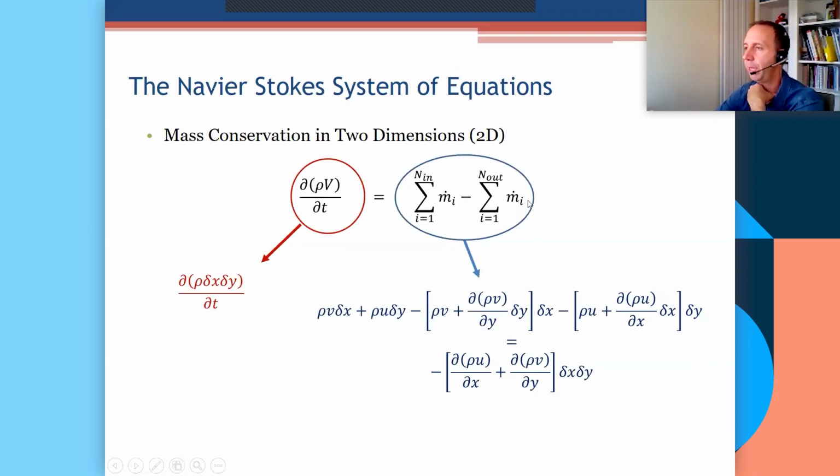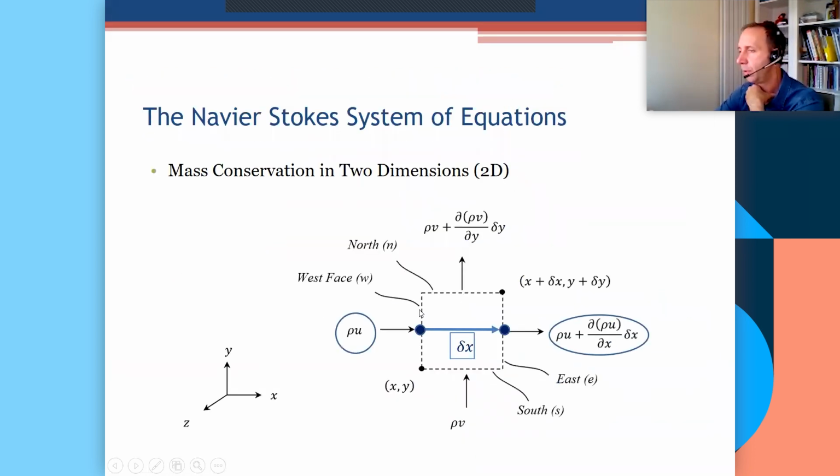The assumptions we've made is that you can say that this quantity is constant over the face. That's true only for small faces. We've also assumed that the only variation in rho u happens in the x direction when we went from there to there. And then the same from there to there. They exist and we can build them in, but it turns out that their contribution, variations along the y, is balancing out because we calculate all that at the center of the control volume.